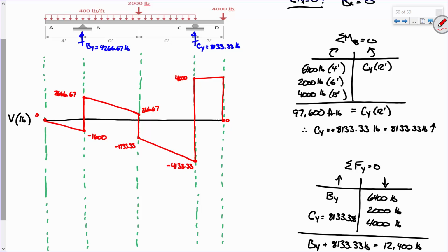To determine whether or not this bridge is safe or unsafe, what we would then have to do is say, all right, here's the shear force. What is the shear stress? And does that exceed limits or what have you? Make sense? All right. Any more questions? This is good stuff.